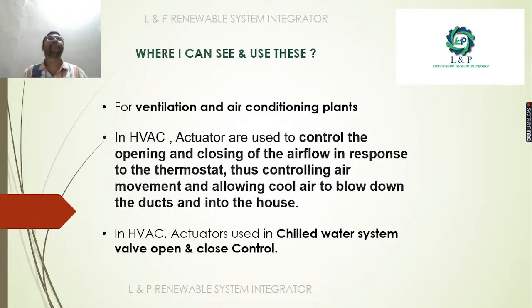It is mostly used in the heating, ventilation, air conditioning industry. And what is the purpose of using it? If you know the amount of humidity present inside the air, with the help of that we can control the temperature in that particular room. So we can control the operation of the cooling coil as well as the hot water coil. In certain places, when and where we need to operate heaters, that decision we can take with the help of this humidity sensor.